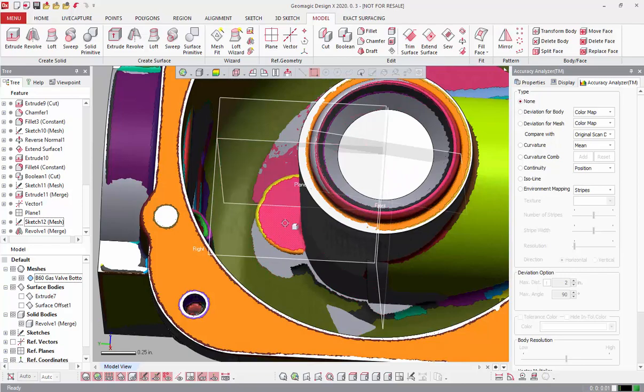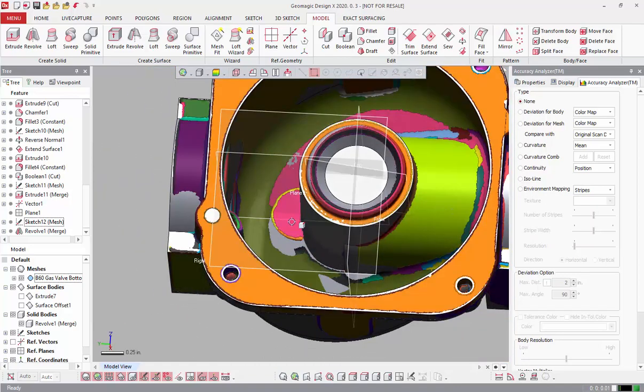I don't always recommend sketching on regions, depending on what type of modeling you're doing. It may be more as-built modeling. That's generally acceptable. What I don't like about doing that with design intent modeling is that there's no way that this plane, the best fit plane to that region on the mesh, is going to be analytically, mathematically, perfectly square with my X, Y, Z, front, right, top planes, or my axes here.